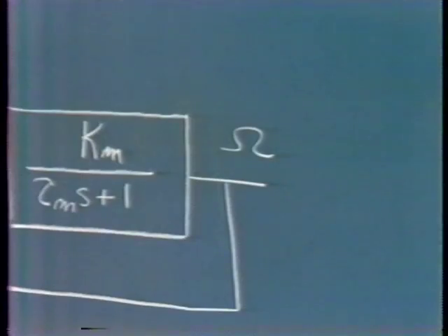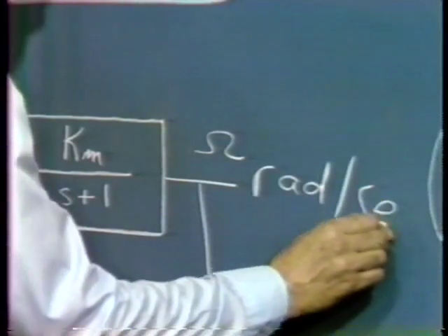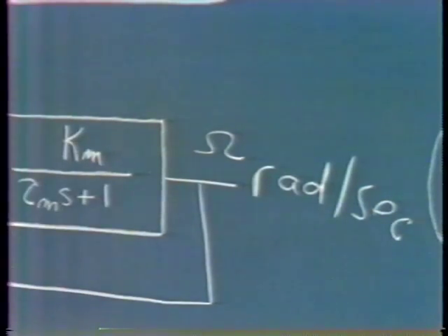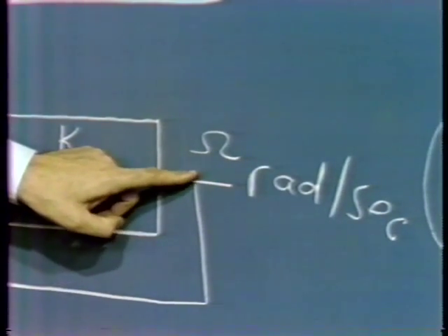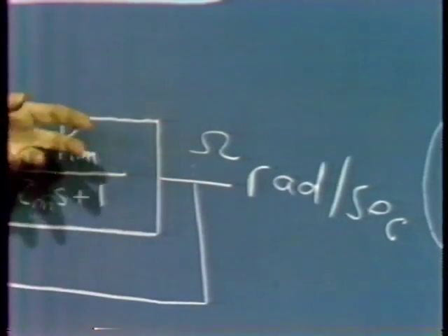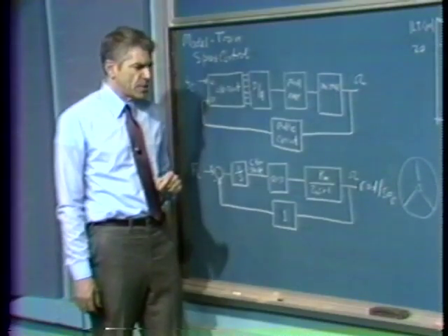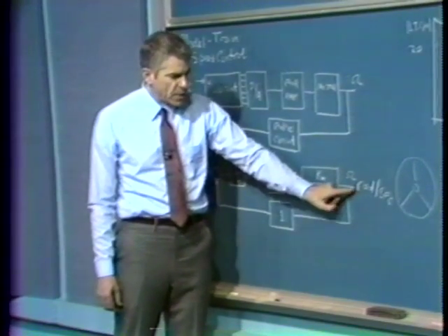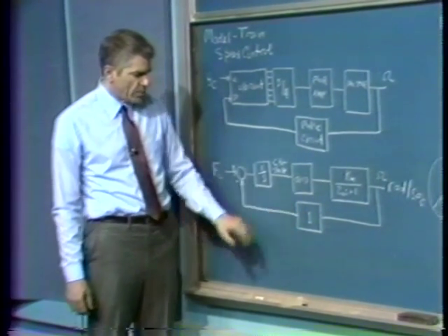Very conveniently, if we consider our speed in radians per second as the units for our shaft velocity on the motor, we find that since we get 6 pulses per revolution, and since 1 radian per second is 1 over 2 pi revolutions per second, a 1 radian per second speed gives me about 1 pulse per second from the pulse shaping circuitry.